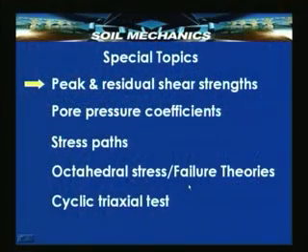And then finally, we will see a very important test called the cyclic triaxial test. These are days when awareness about earthquakes and their damage has increased like anything because of recent experiences. The cyclic triaxial test is useful in determining the liquefaction strength of a soil. It helps us predict under what conditions a soil will liquefy and whether the present condition is indicative of a potential to liquefy or not.